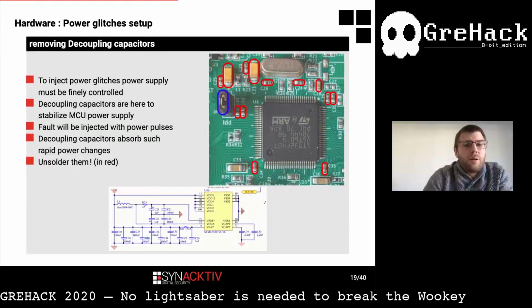Short power cuts are not wanted in normal operation, and so there are many capacitors on the board to stabilize and filter the power supply. And to inject a power pulse, we need to remove them, so we just unsoldered them.